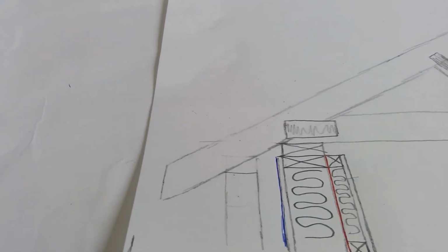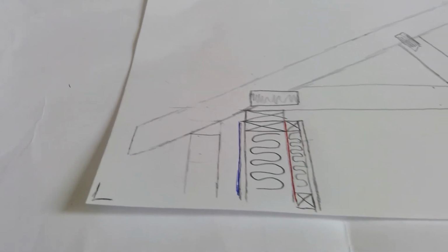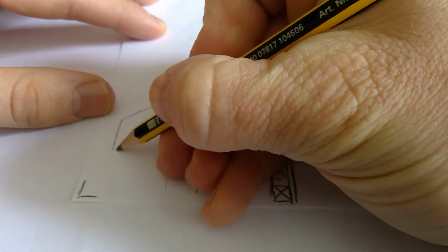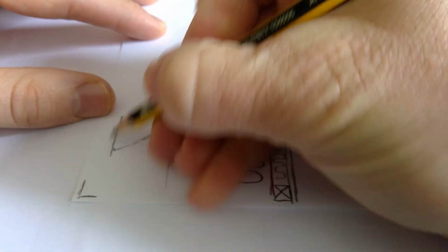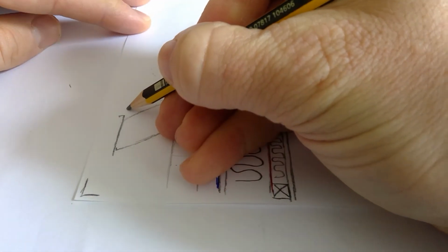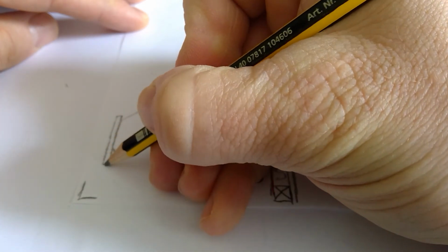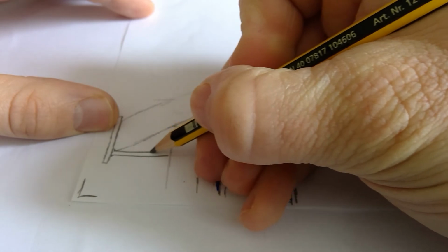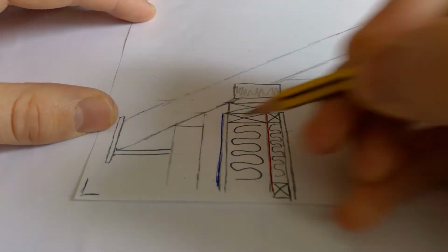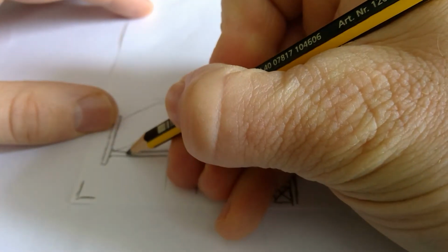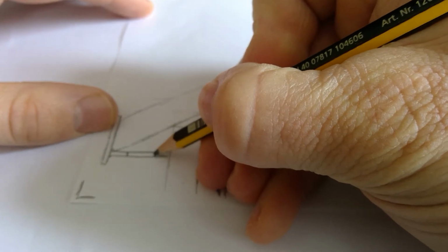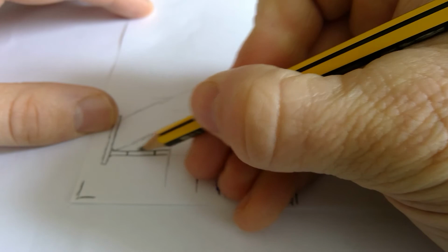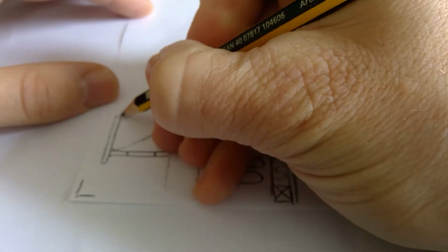Then we come over here. We have to get our soffit and fascia and slates. So again, how far down here do we go? You make a judgment yourself. 25 mil fascia. It goes a little bit above the rafter. Come down there, a little bit below. 12 mil soffit. Coming along there. Alright, there's a vent here. The question specifically asks you to show the ventilation path, which we'll show in a minute with a ventilator. Make maybe a 60 or 100 millimeter vent there, you can decide.